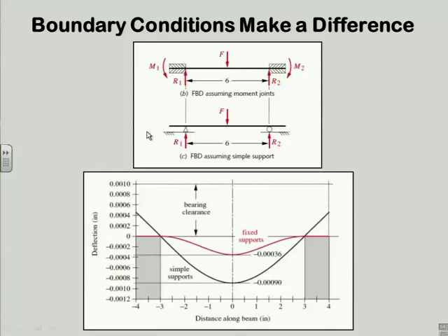So simple problem, I can solve it by the classical method, and I do that with the appropriate equations. And for the fixed supports, I see something that looks like this for deflection. It's about 3 10,000ths of an inch, or 4 10,000ths of an inch with the other figure, and about roughly 3 times that, or 2.5 times that, with the simple support. Now, you should expect that you would get more deflection with simple support, right? Because the beam can change slope at the supports.